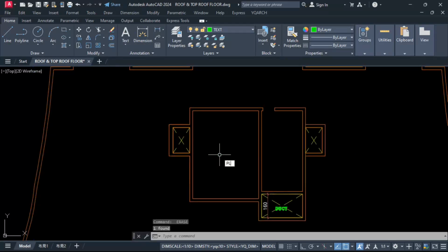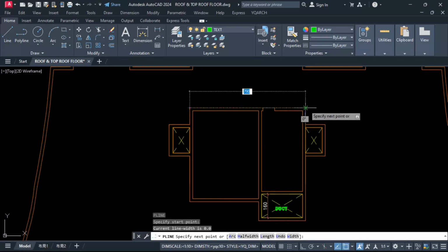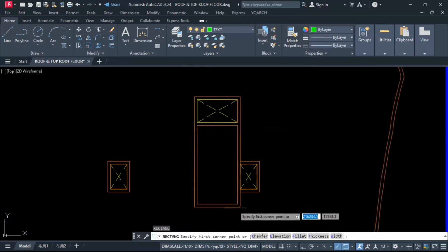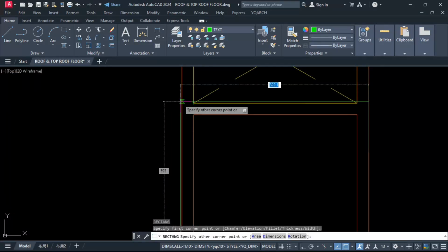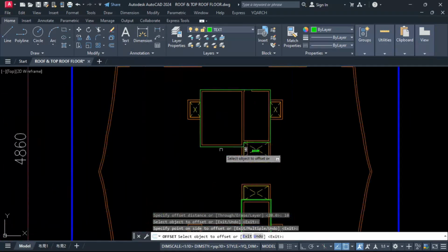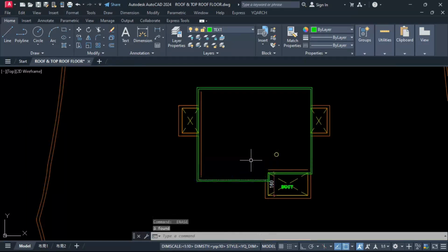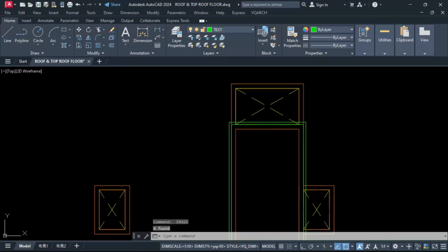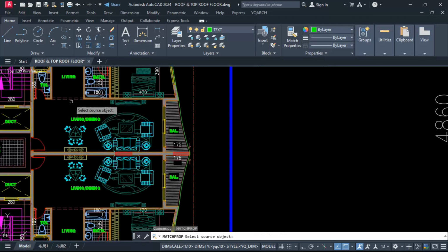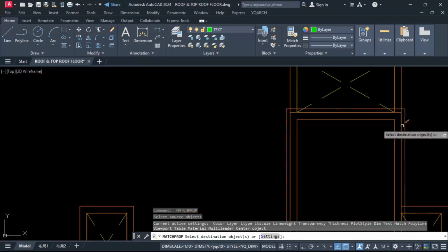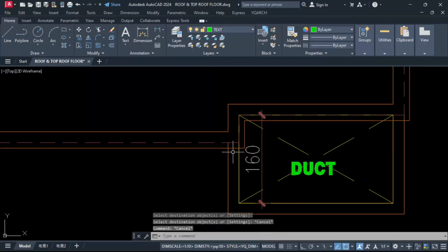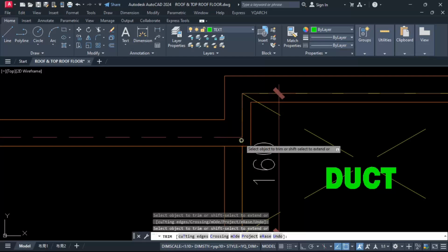Remove the dimension here also and use a polyline. We'll showcase our little projection area for our top floor parapet, okay. Same as it is here also, take a rectangle up to the staircase plan. Now offset this 10 centimeters outside. Remove this fully, okay. And offset again 20 centimeters, okay. Here also. And simply match, and take any dash line to showcase our inner hidden line. This is our wall line, okay. And the rest simply trim.